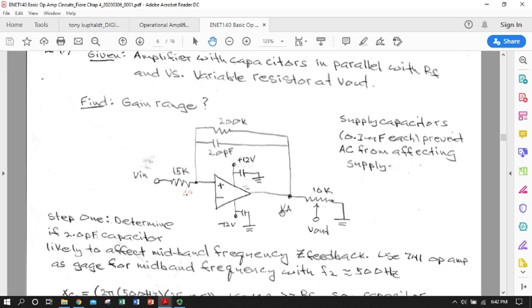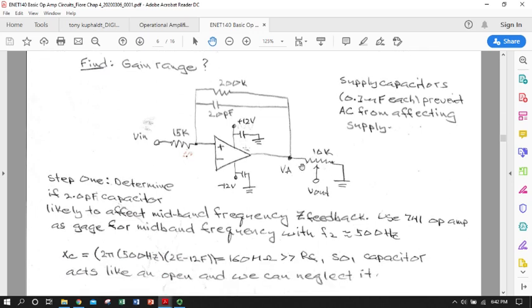So if you had like a 1 volt DC signal coming in to point VA, you would end up with a signal at VA equal to negative 200 over 15, and then your output going out into your circuit would be dependent on how much of this 10K pot you were selecting. So this is just another nuance on the inverted amplifier, and just shows a little bit more selective version of your load resistor. Let's see if there's anything else super important.